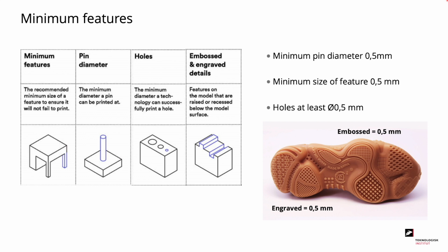That's because the minimum pin diameter is 0.5 mm. The minimum size of a feature is also 0.5 mm. Holes should have a diameter of at least 0.5 mm. And for embossed and engraved details, the height, depth and width should also be, you guessed it, 0.5 mm.